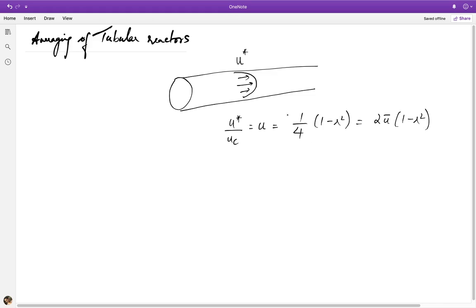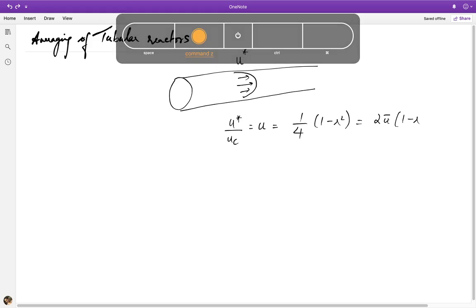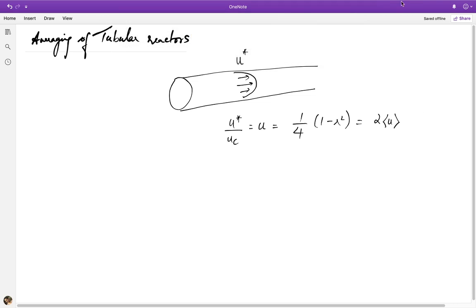So you can show that the average velocity after integrating this is 1 by 8. So the average velocity here, I'll use a consistent notation with what we use for cross-section average, which is these angular brackets, times 1 minus r square, where the definition of this cross-section average is 0 to r of u r dr, divided by r dr. And this you can evaluate, so this is not 0 to r, it's a definite integral, so it's 0 to 1 in dimensional form.